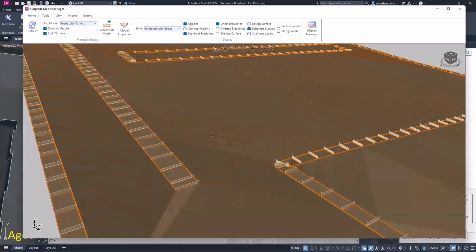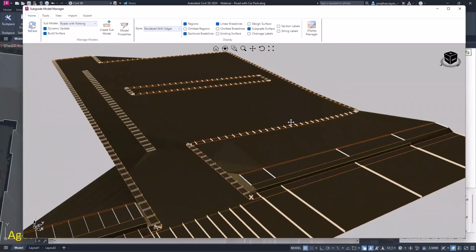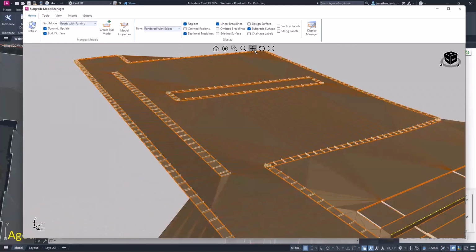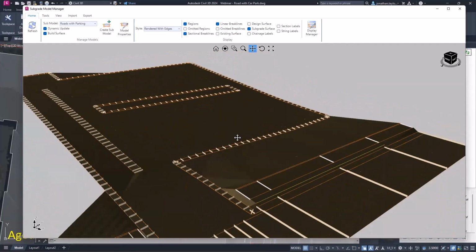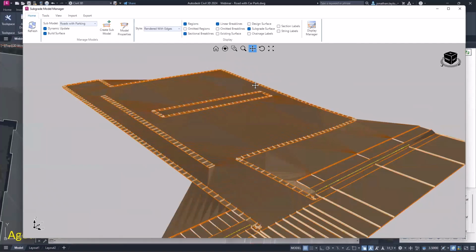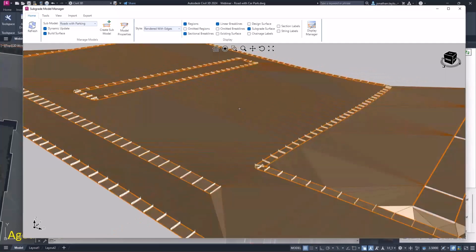And this basically means I can start to click on things and pick things in the drawing. Because of that, the pan functionality is not on the left mouse click. It's actually holding down Control on your keyboard and then holding down the mouse wheel, and that gives you the pan. Now, if you do find yourself attracted to this button here, that's fine. You can use the pan, you can orbit, and you can operate with your left mouse button, but you won't have the picker tool. So click on the Home tab, and that reinitiates the picker tool, which means that you can then begin to select objects, which is the whole point of this environment, to be able to select things and turn things on and off.